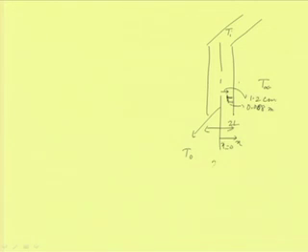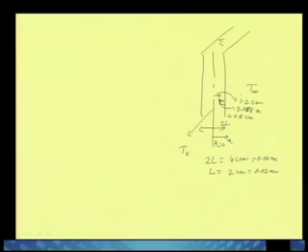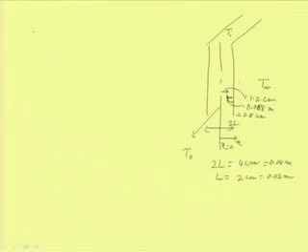The reason is 2L is given as 4 centimeter, which is equal to 0.04 meter, L is equal to 2 centimeter, which is equal to 0.02 meter, and the second part is 0.8 centimeter, which is equal to 0.008 meter, and from the center line it is 1.2 centimeter. So, the first part is A, where we have to find out the center line temperature.